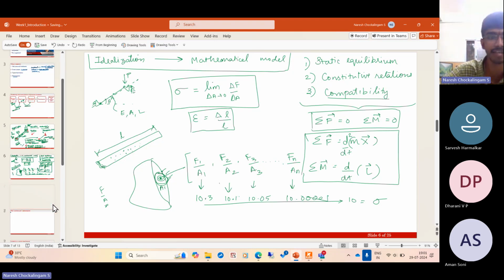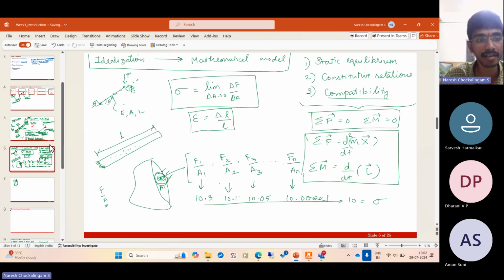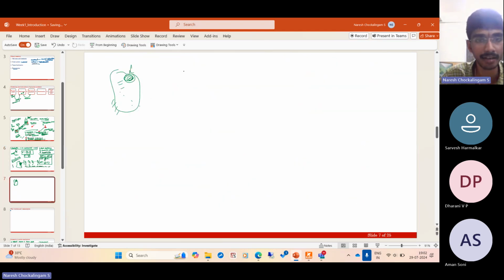But if you look at some of the finite element plots, you get a strain field. You get different colors, right? So you have some body subjected to some forces. You see the strains and stresses are very high here, and low somewhere else, which means strain is also a pointwise quantity. Multi-dimensional strain definitions need the concept of tensors, which comes in the next week. It's week 2 content, so we'll look at it next week.